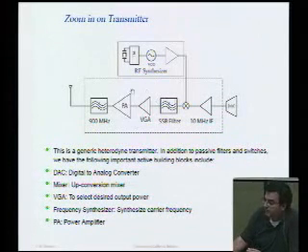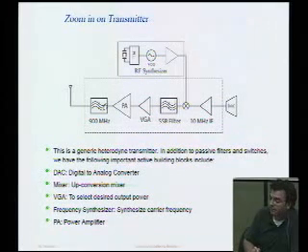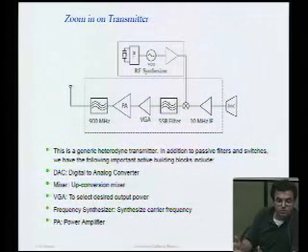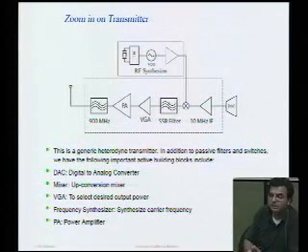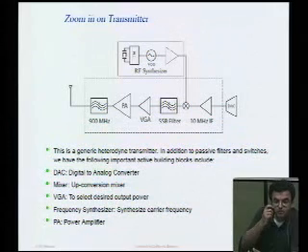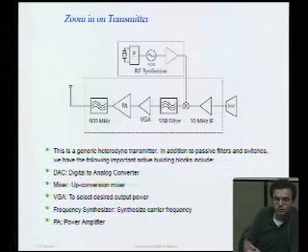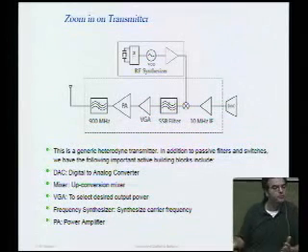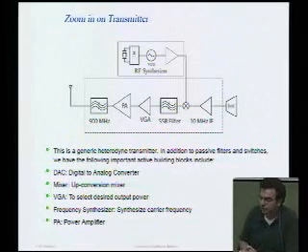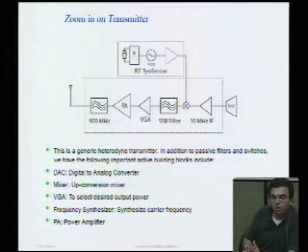And finally, we run that into a power amplifier. A power amplifier is designed to put out a lot of power into the load. The load might be the antenna, it might be the cable that it's driving, but usually we'll find the load is a relatively small impedance, something like 50 ohms, 75 ohms, or 300 ohms. If you're looking back to your analog course, most of the loads that you're used to driving are capacitive loads, right? Or high impedance loads. In this class, often we'll be driving low impedance loads.